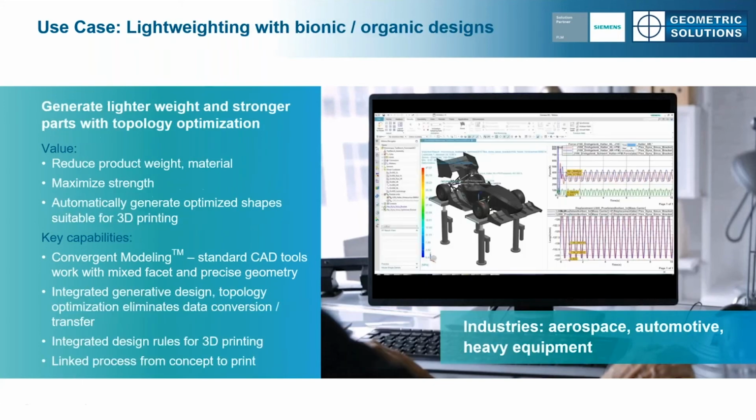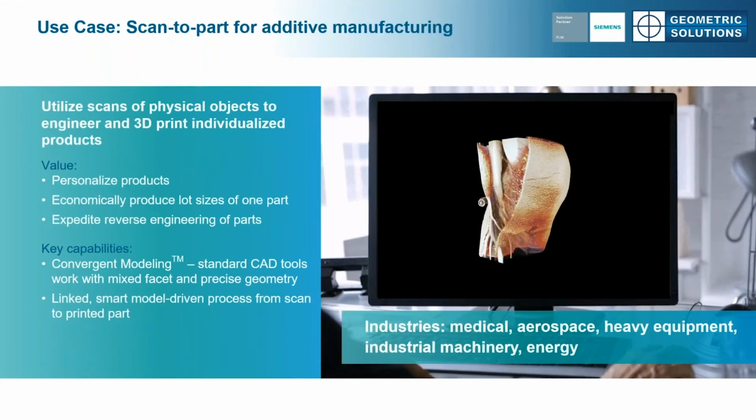So Dan, I saw that blue material on here. Was that the support material to hold it up while it's printing? Yes, yep. And that's the nice thing about NX. I'm glad you pointed that out, Curtis. With NX, once you create your part, you then go through those checks, and it's going to show where you need support. Because if you put support everywhere, it's going to be too expensive. But if you don't put support in the right spots, the part's going to sag. It's not going to work. So that's another cool thing with NX being that end-to-end solution.